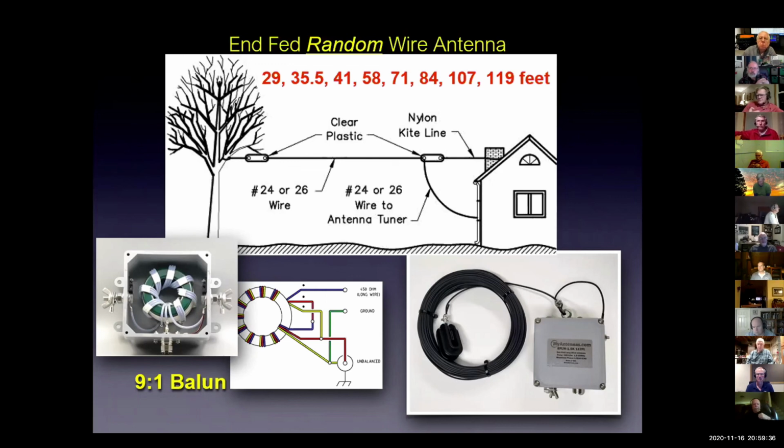As far as that transduction efficiency is concerned, a resonant antenna does a better job, and I've looked at it with a field strength meter. The bottom line is that a resonant antenna does a better job of transducing energy into the atmosphere. Even if you're using a tuner on a less resonant antenna and getting a good match with your transmitter, the antenna just doesn't put as much energy out into the atmosphere as a resonant antenna does.